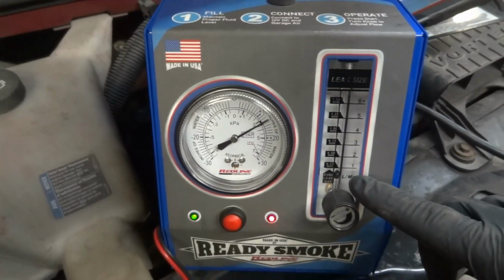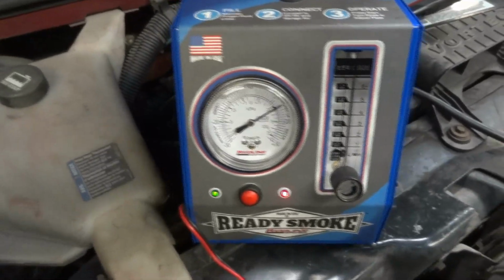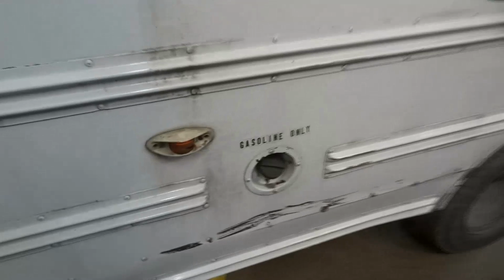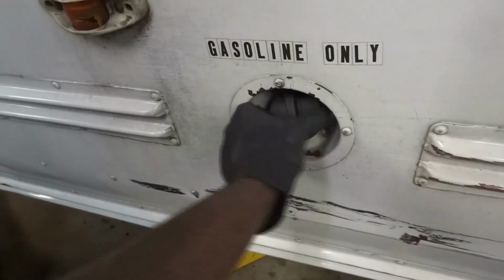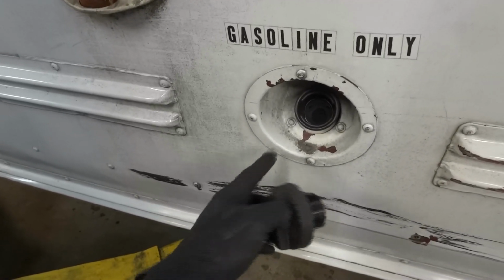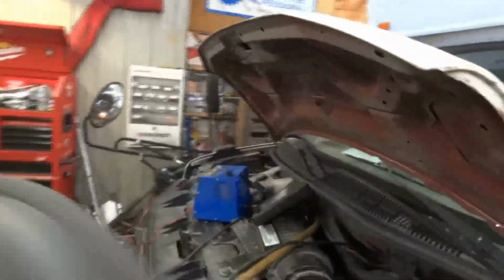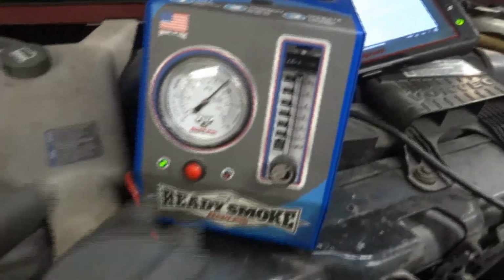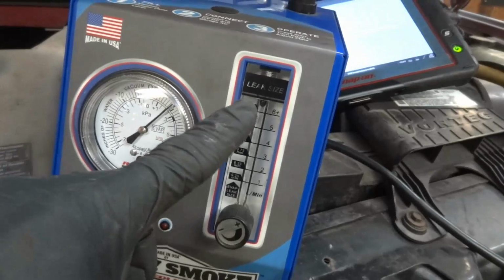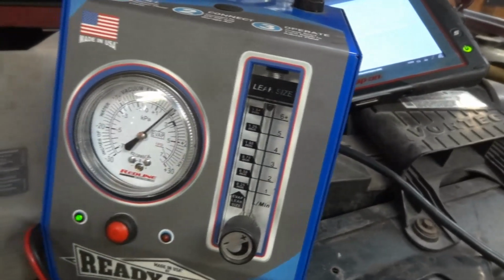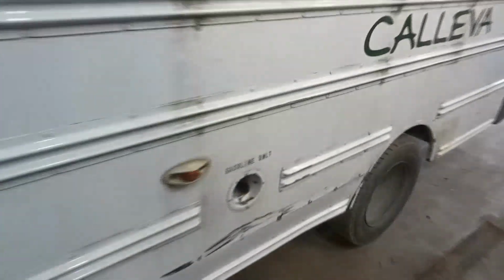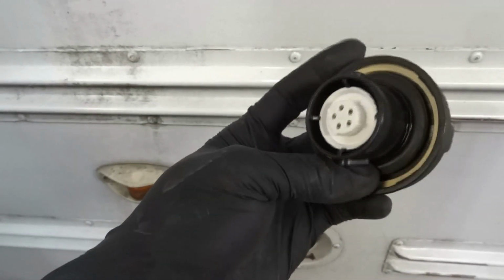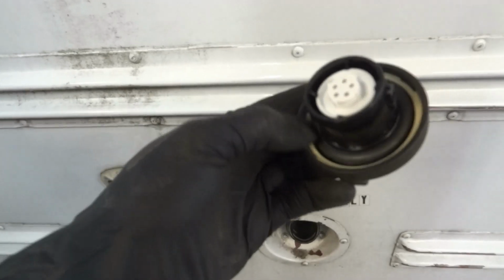Usually when I see the check ball going down low like this, the problem ends up just being a fuel cap that's not sealing properly, or that maybe wasn't turned all the way tight at some point. So let me open this and see what happens. I hope you guys heard a vacuum. As you can see, there's smoke now coming up. If we go to our smoke machine, there will be a big leak on the smoke machine right now. So right now, with the gas cap removed, our check ball went back up to the large leak reading. So now let's go back and install the gas cap. It should drop. Okay, and I'm inspecting the seal around the gas cap, and the seal doesn't look bad.